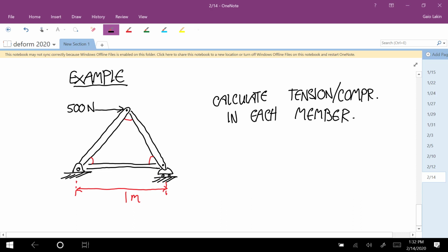Okay, before I do that, with this approach, assuming that the weights here are negligible compared to that force, we can use the truss simplification. But if we wanted to calculate what would happen with this 500 Newton force down here a little bit, we can't use the truss simplification. Or if one of these was heavier and we wanted to include the weight in one of those members or something. So this truss simplification is very picky. And that's something you definitely need to be aware of.